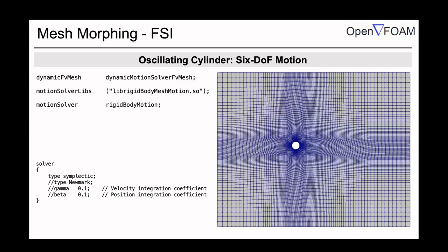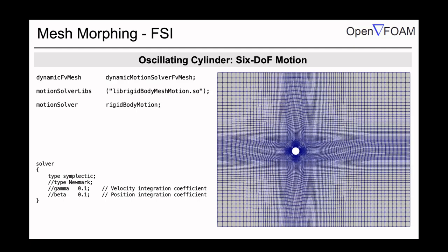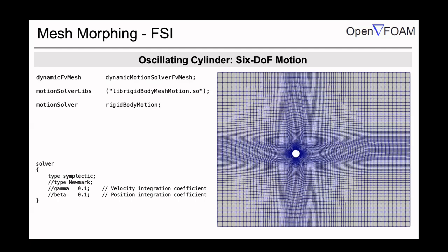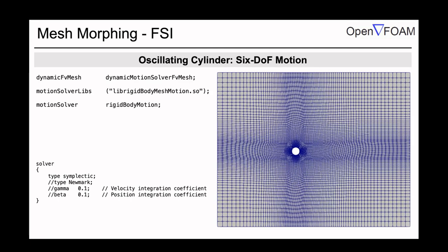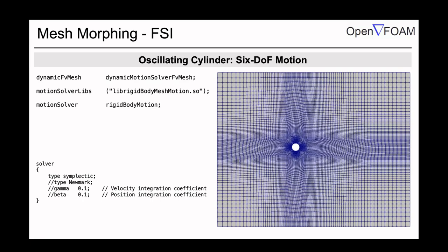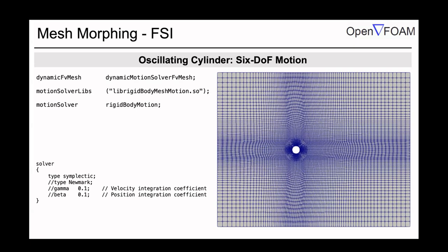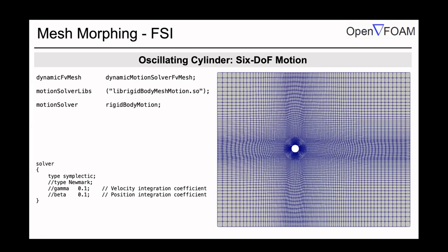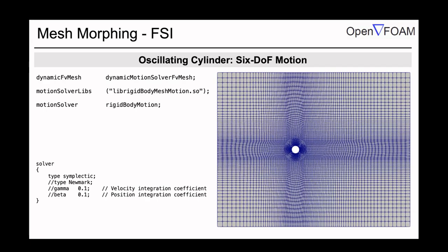In the tabular form, does it assume there will be a linear interpolation? Yes. If you give a big gap between time, it just interpolates, which is not expected. So a similar approach can be used for FSI calculation with limited degrees of freedom, of course, not continuous flexibility. Here, what changes you have to make is that the motion solver will change to rigid body motion, or 6 degree of freedom rigid body motion.